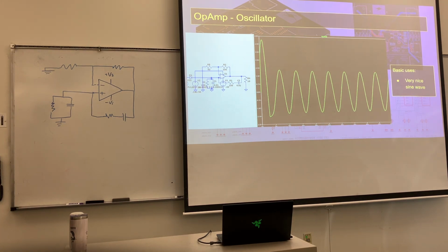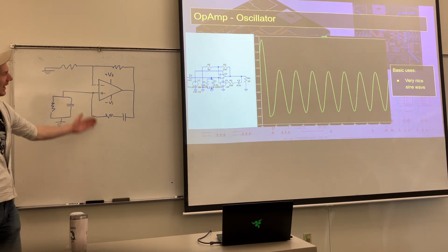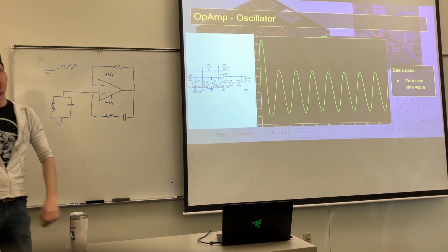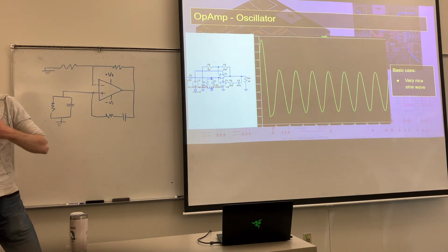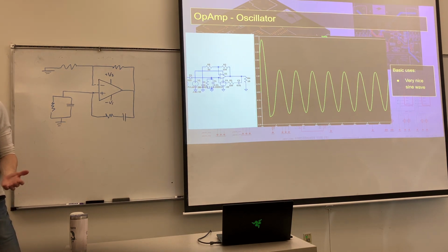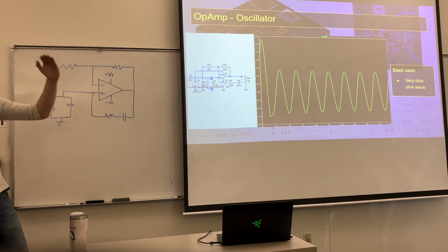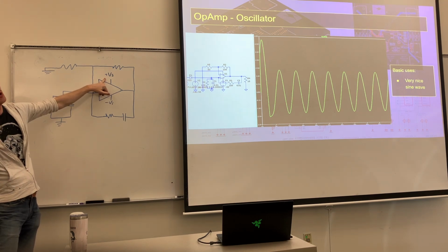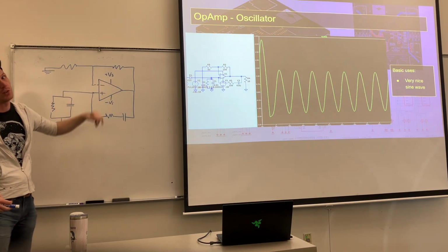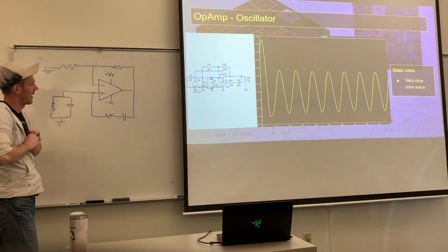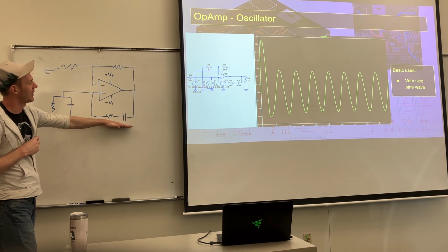And in real life, there's the ideal op amp that has infinite current output potential and infinite voltage supplies. And that's a little silly. In real life, you'll have a voltage and current rating assigned to the op amp, at which you'll say, okay, I can only do 1 amp, which is the case for ours. There will be bands in which you can only have these voltages be 20 volts apart, or no more than 10, or no more than 10 millivolts in some cases, or smaller. But remember back again to kind of what we said in the very first lecture.